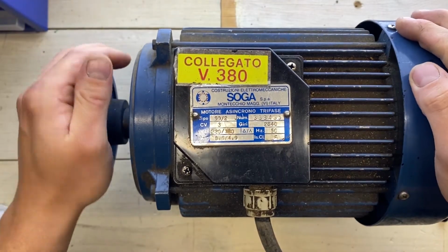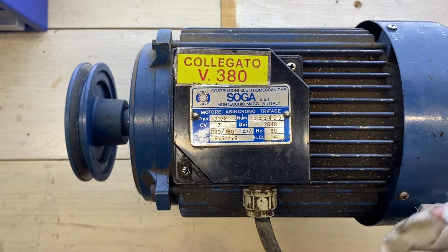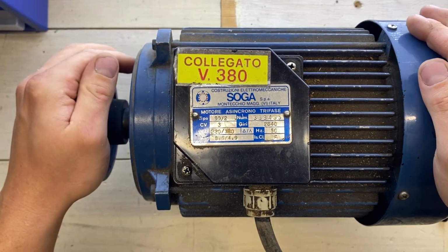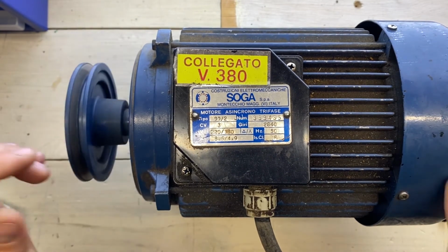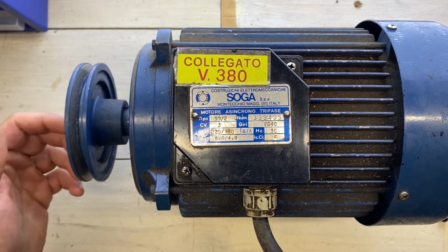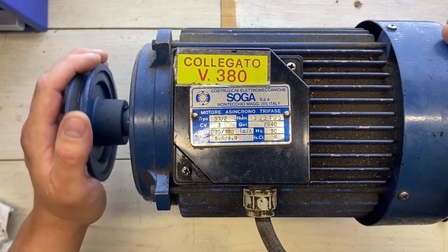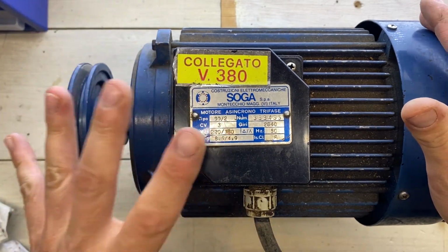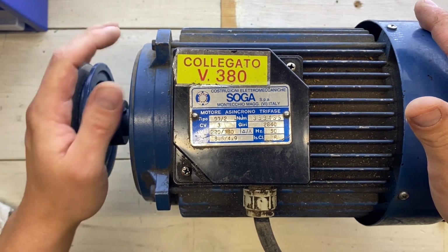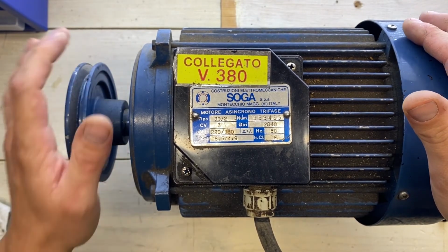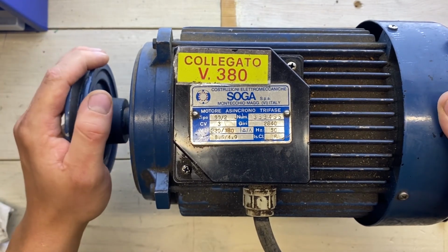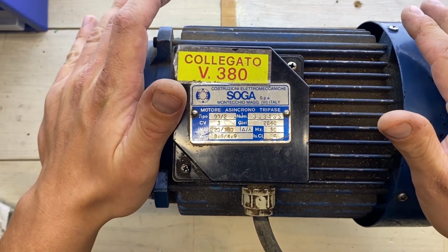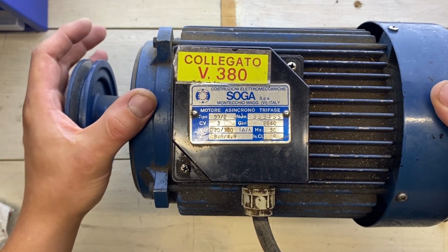Now, to use one of these in your home-built machine, you will need either one of two things, or I should say 3 things. You will need either a contactor, that is basically just a big relay used for turning on and off power loads. You will need a soft starter that I can explain at a later date, or you need a variable frequency drive. And the first two have the downside that you will have a fixed speed on the motor, you can't change it. But if you want to change the speed of this motor, you will need to change the frequency of the incoming power. And the most common way of doing that these days is with a variable frequency drive.